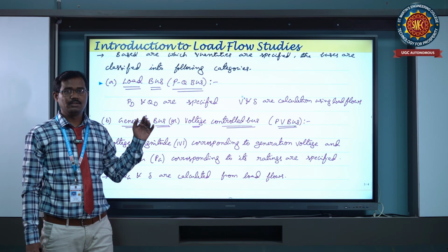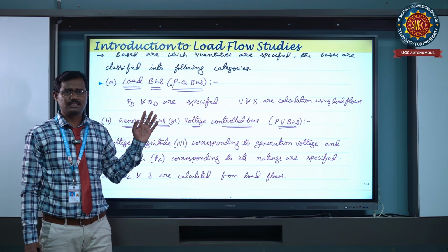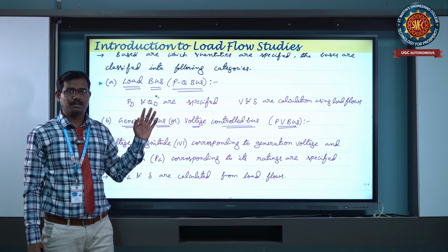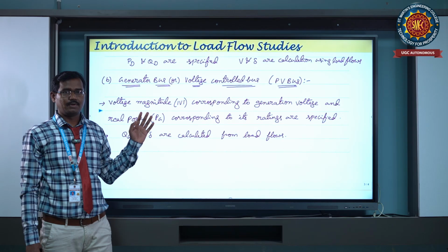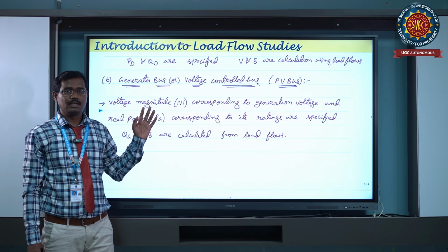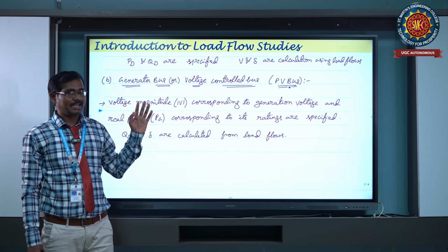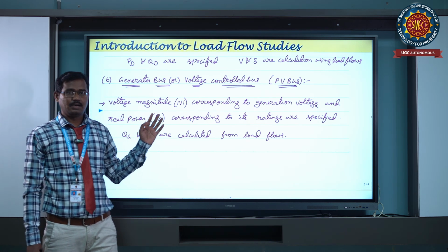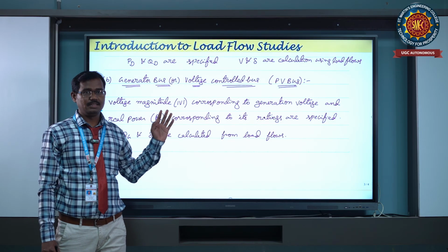Coming to the generator bus, this is a bus at which we can connect the generators, and at which the magnitude of voltage and the active power are specified. These two quantities are specified, and the other two quantities are to be obtained in the system.